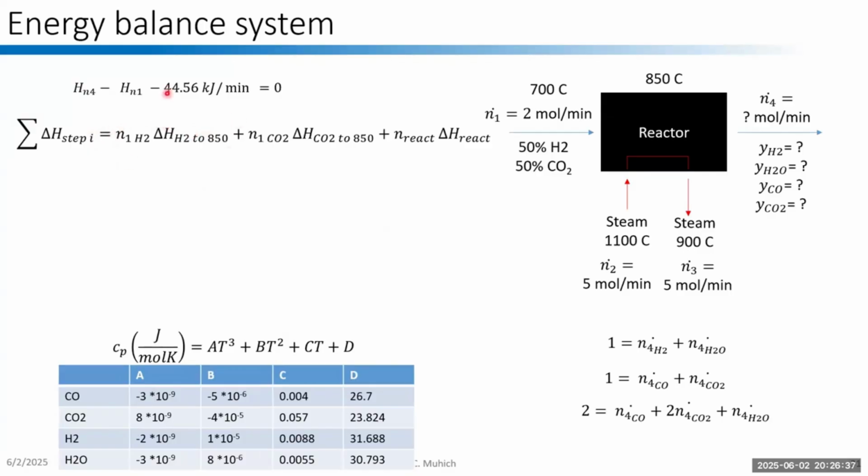All right, so let's tackle first this temperature change. My temperature change of heating the hydrogen is going to look an awful lot like the temperature change associated with the steam. I have my molar flow rate of hydrogen, and I'm taking my integral this time from 700 to 850, because I start at 700 and go to 850C, and then I correct that by this plus 273 in order to move to Kelvin.